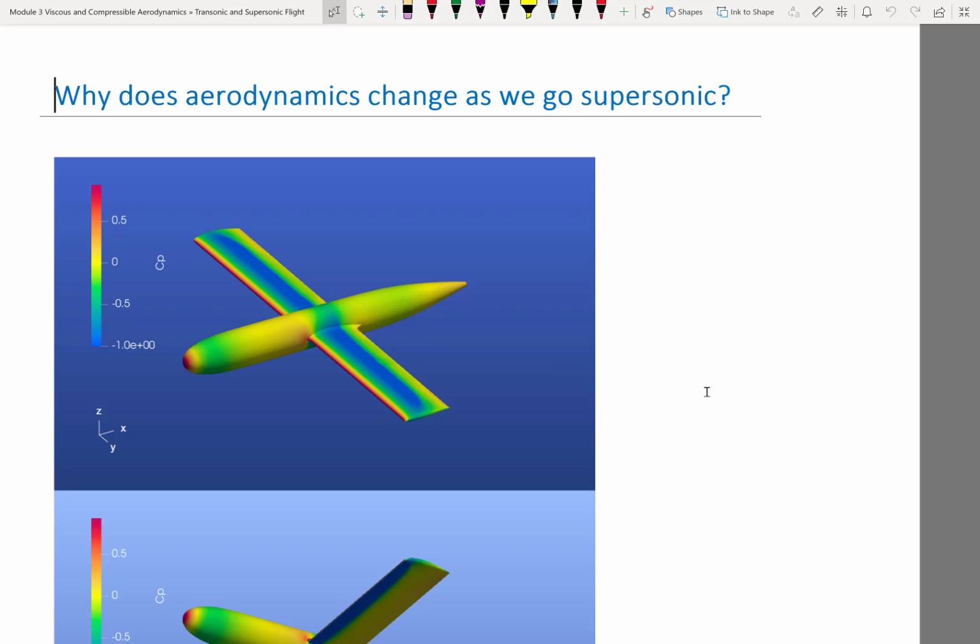And as we are going to see a little bit later, if we have a horizontal tail over here, at this Mach number, the horizontal tail would also suffer from a loss of control authority. So this effect would push the nose down at the same time when the pilot is having a harder time pulling the nose up, right? So this is a big and significant effect, that the center of lift is shifting backwards.